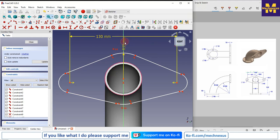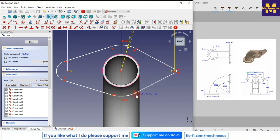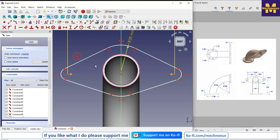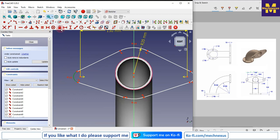Now I will move my dimension to the outside. Now this radius and this radius are R15, so first I will make them equal, and then one of the radii I will give R15.